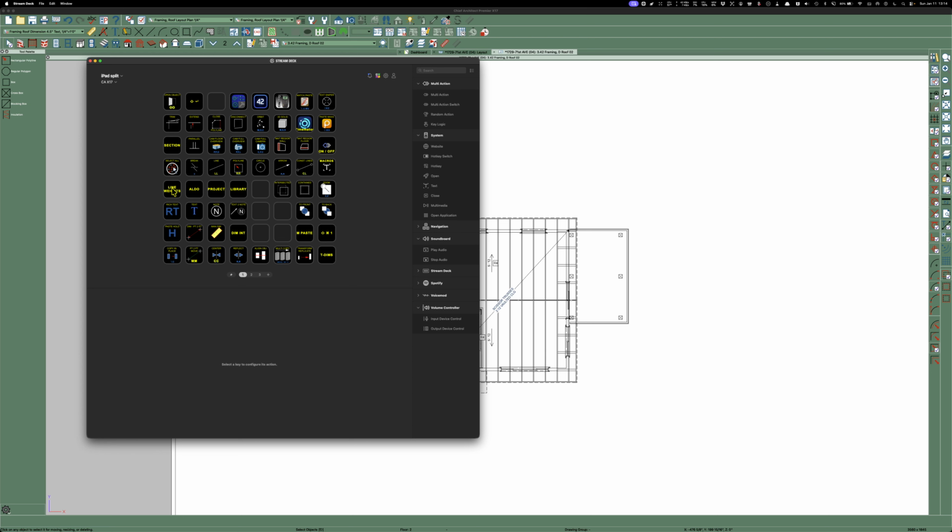I've noticed I like to turn line weights on and off sometimes because I want to get exact with the skinny little line before the big fat line just makes it impossible. I can turn on and off the active layer, display, the project, and the library. So they either pop up on my screen or go away.